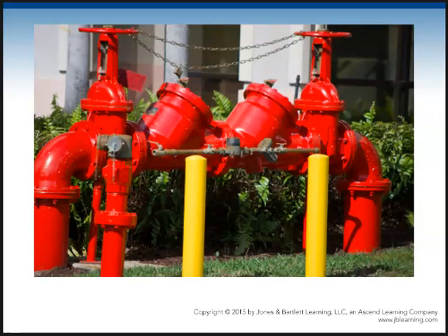Now, in the front left side, you can also see a fire department connection. And that is where the fire department would connect. So you know that that side is the side that's going to the building, because they want to make sure that that also is not going to go back in the domestic system. So it's after the backflow device, making sure the water can't go back into domestic water, because it would basically poison it. It would basically pollute it. The fire department connection is there so that we can increase the pressure in the standpipes or in the sprinklers.